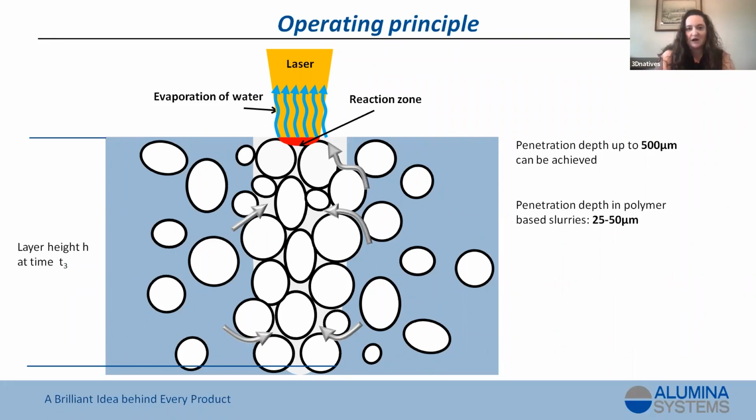One last question, because I think we should wrap up. What would be considered a standard temperature program on the shop floor, and what is the debinding and sintering temperature in that one-step process? The debinding temperature is about 1000 degrees C, and the top temperature for sintering is around 1650 degrees C. Of course, we have our own sintering curves for how we do that, in what time and at which ramp we go up to the temperatures.